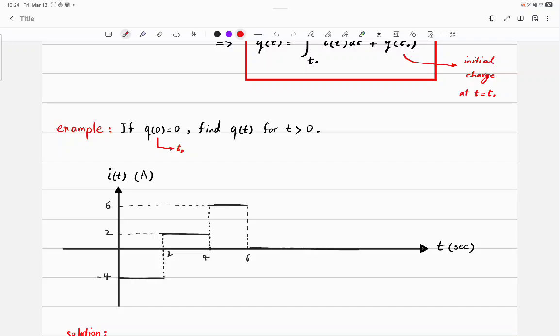So for this case, let's not look at the values. The black current is entering from the negative terminal. What does it mean? If I multiply the associated numbers, what kind of power will it give me? Supply. How do you find the absorbed from that? Add a negative sign. Did that make sense? So if there is some confusion, it's normal. The only thing that you can do to decrease that confusion is just do more examples. So, what is the power absorbed by element A?